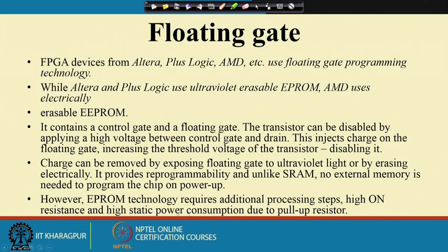This EEPROM technology requires additional processing steps, and of course there is high on resistance and high static power consumption due to the pull up resistor. So, this is the problem with EEPROM technology that is there with floating gate based FPGAs.